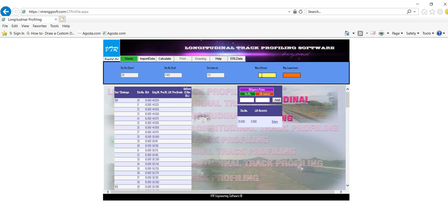Practically that is not feasible and we cannot afford that much. So normally for smoothening, when the existing surface is there and you just want to correct some modulations, it is fine tuning, so you can give some minimum lift. Lowering also works like that. Sometimes we cannot cut the surface but we can do the lifting, we can raise the level. If you want to permit lowering, you can permit how much cutting is allowed. That option is also available.